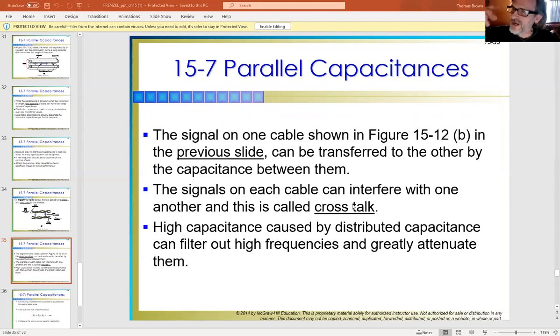And then I decide, oh, I'm going to put my cable and telephone lines right with them. No. The AC EMF will literally garbage out your cable transmissions, your telephone ones. So it's actually NEC code: 48 inches, 4 feet away if you're going to run them parallel like that, to get rid of that crosstalk.